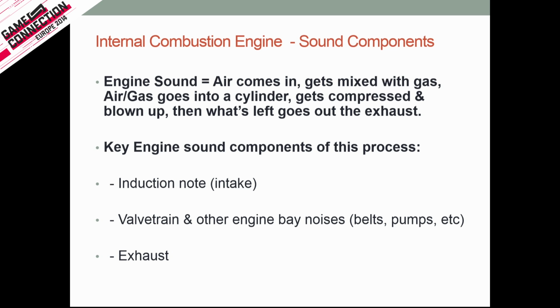And what we care about out of this, in terms of the sound components of this process, there are some things that weren't necessarily obvious to me before I started making racing games about how an engine made sound. A big one is actually the induction note. The induction note is the sound of air rushing into the engine. This is a primary sonic characteristic of a lot of engines, and we usually mic this up. This is an actual tube, and you'll see a picture of it here in a minute. It routes air from the atmosphere right into the intake plenum of an engine.